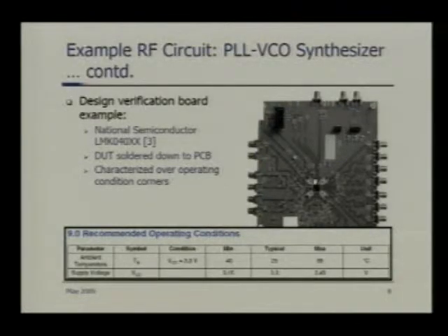Okay, so using contactor, you may come up with values that are not true in real life application. So the best possible scenario is to use the soldered down part on the PCB fixture and do the characterization, but it comes at a price.